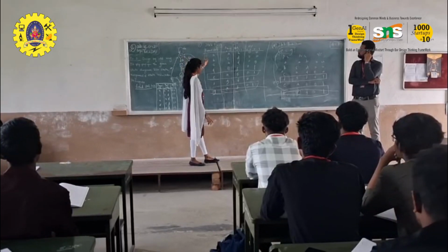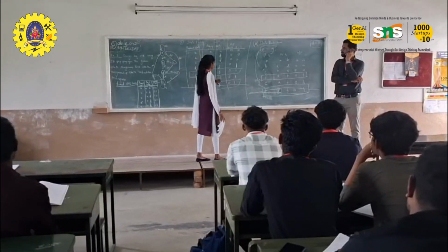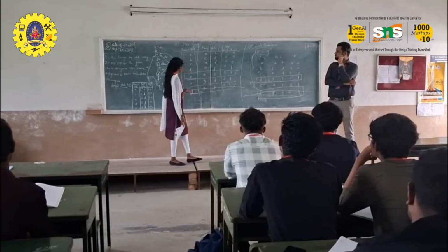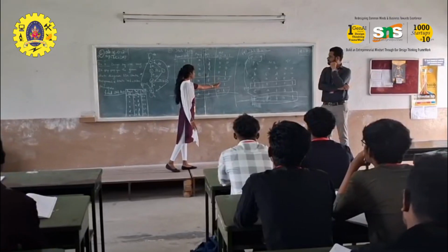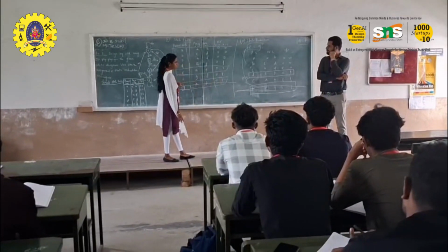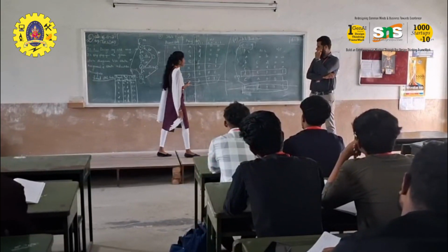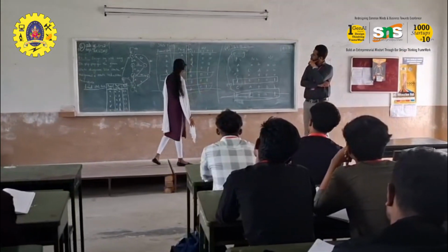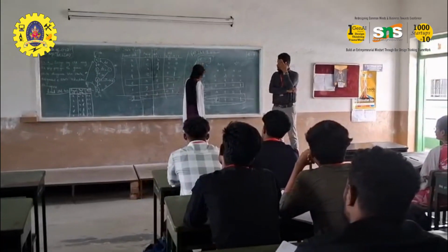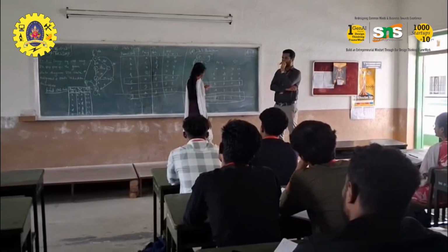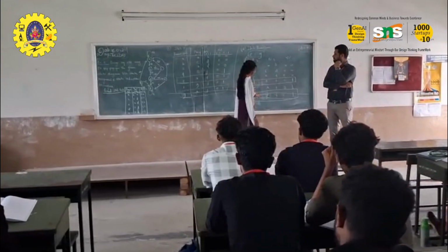For the other present states, we follow the same steps. Next we finalize the state table. Then we check which present states have the same next state and outputs, for inputs 0 and 1. E and G are both the same. We want to eliminate any one state, so we choose G. Next we go for the state reduction. We assign both states as equal, so E is equal to G. We eliminate the G state, so G is replaced by E.